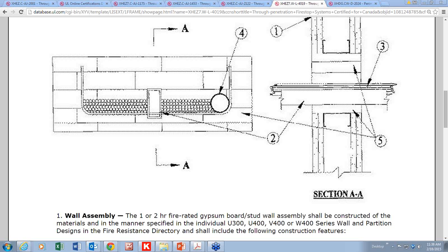Yeah, basically, a stacked bond, if you had a 4 by 8 inch block, you would stack one directly on top of the other with no staggered joint. A running bond basically calls for joints to be staggered by 50% of the length of the block. So you'd always have a 4-inch overlap in a 4-inch by 8-inch block.